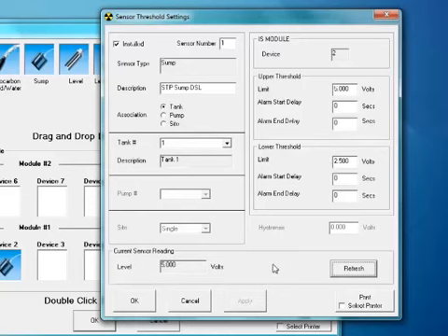So in normal operation, when this sensor opens, then our voltage would go down to 0 volts. When it goes down to 0 volts, we would go into alarm. When it's closed, we are reading 5 volts. If our power supply was putting out a little bit higher voltage than 5 volts, say 5.1 volts, in a normal condition, we would go into alarm. So what you want to do is look at your threshold limits and then see what the sensor is reading in its non-alarm state, and then you can adjust those accordingly.